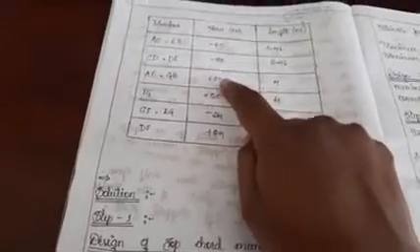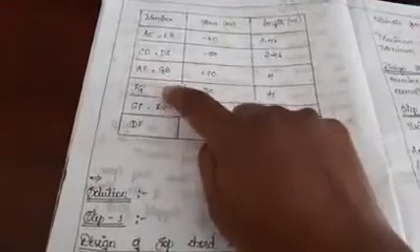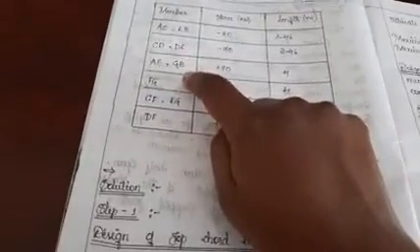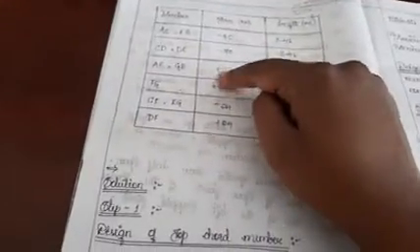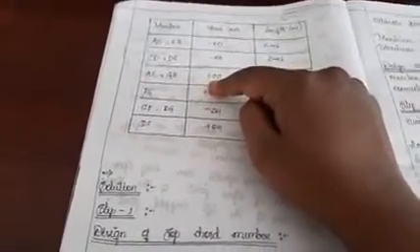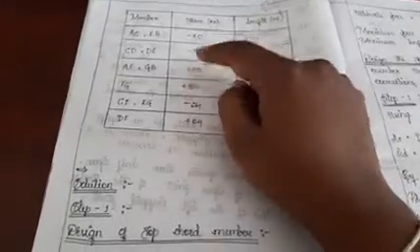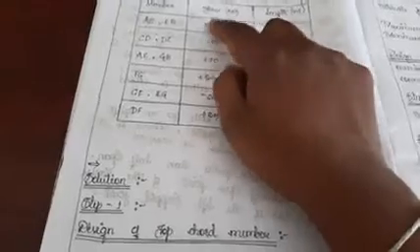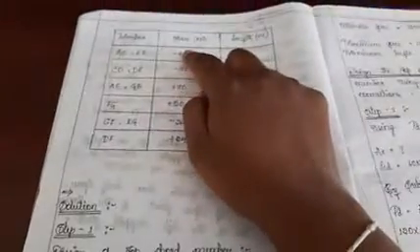So you need to do the design for the bottom member as a tension member. Tension design has to be done. Okay, whatever procedure there is for tension member design, you have to follow that. Whereas for this top chord member, it is subjected to a compressive force. It means the force which is shown in the table is negative.